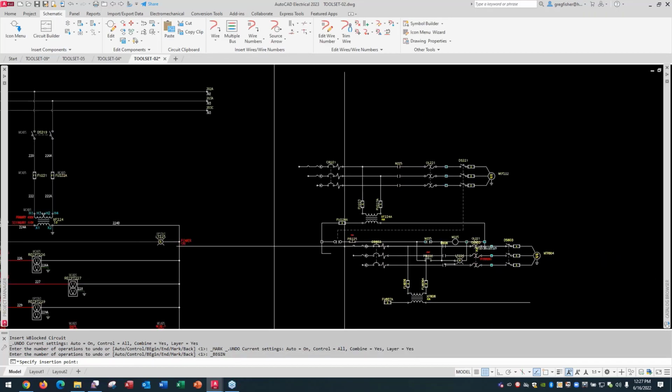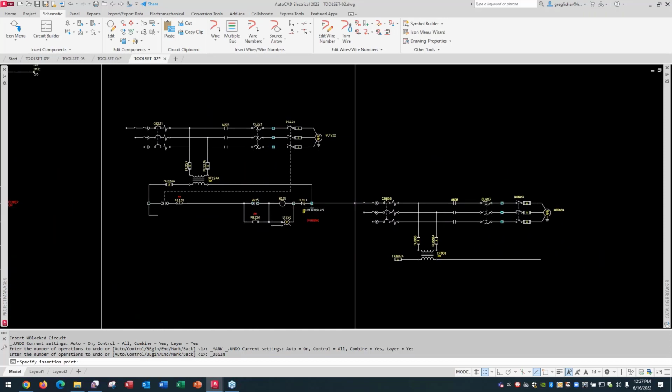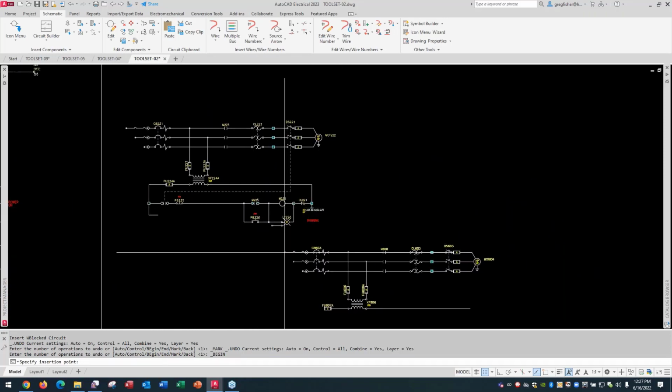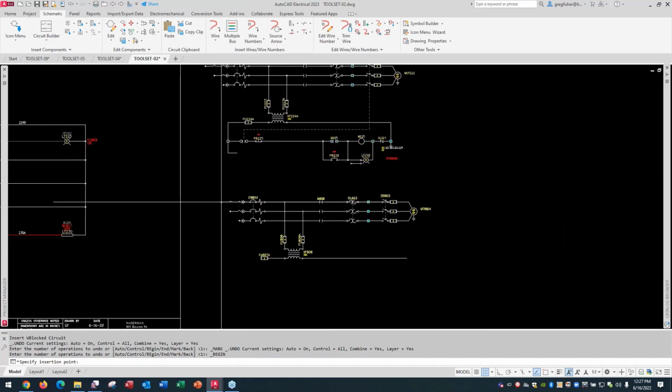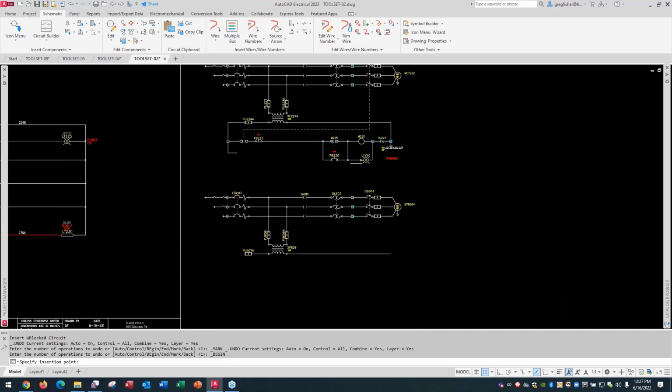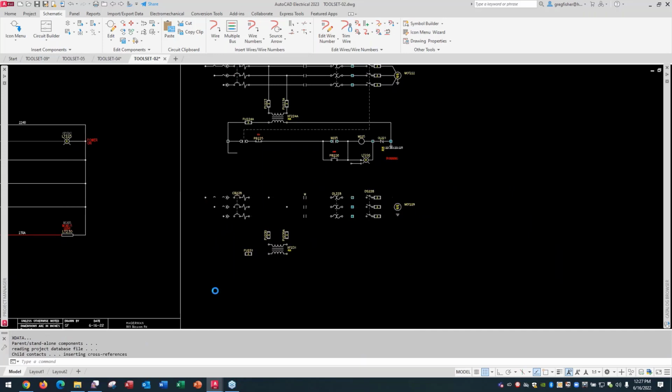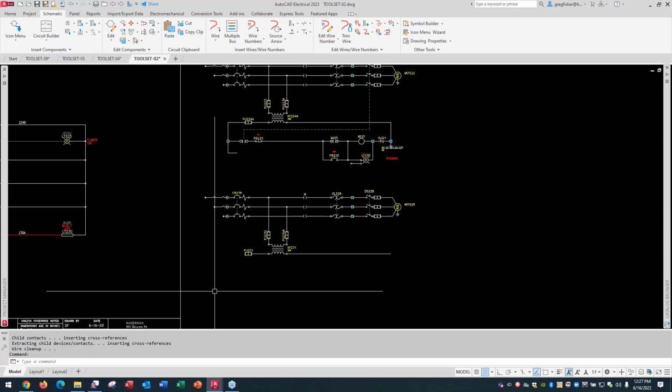it's similar to the one above it with all the other components on the secondary there. But the main point is, if you have any types of circuits, you can save them as a circuit. You can even build them into a drawing template. So when you start a new drawing, you can have circuits already started. Half your work could be done when you place these into a drawing template to use to create a new drawing.